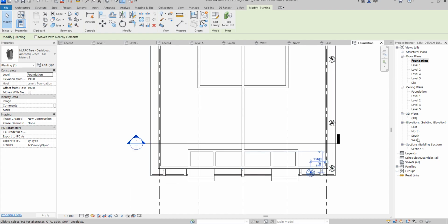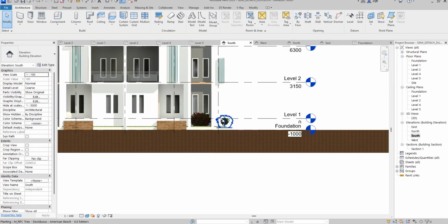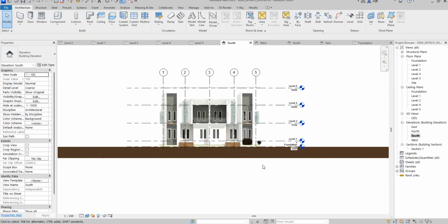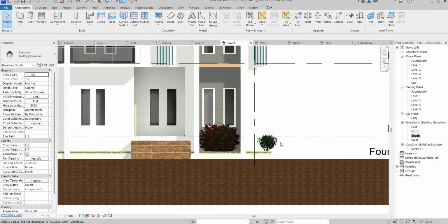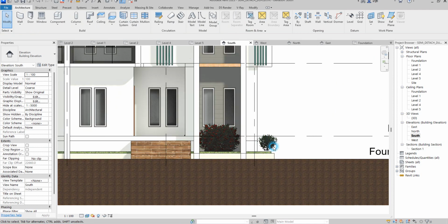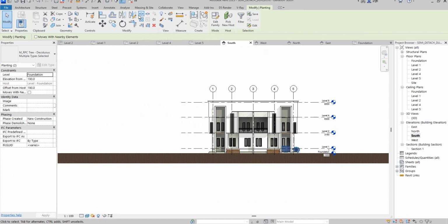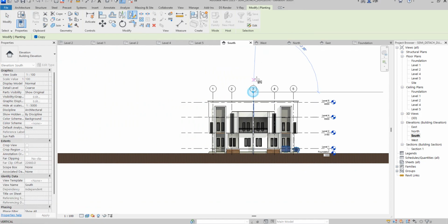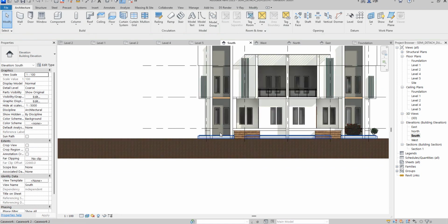Now I want to show something. There is an issue when you mirror flowers. You know, I've been doing mirror. When you mirror flowers, it will not show in the place you mirror it. Let me give you an instance. When you click here, like this too, I click this one too. So if you mirror it now, you are not going to see it, which is very bad. The reason why is by using image base. Can you see? It's there, but it's not visible. Even when you render it, it's not going to be visible.